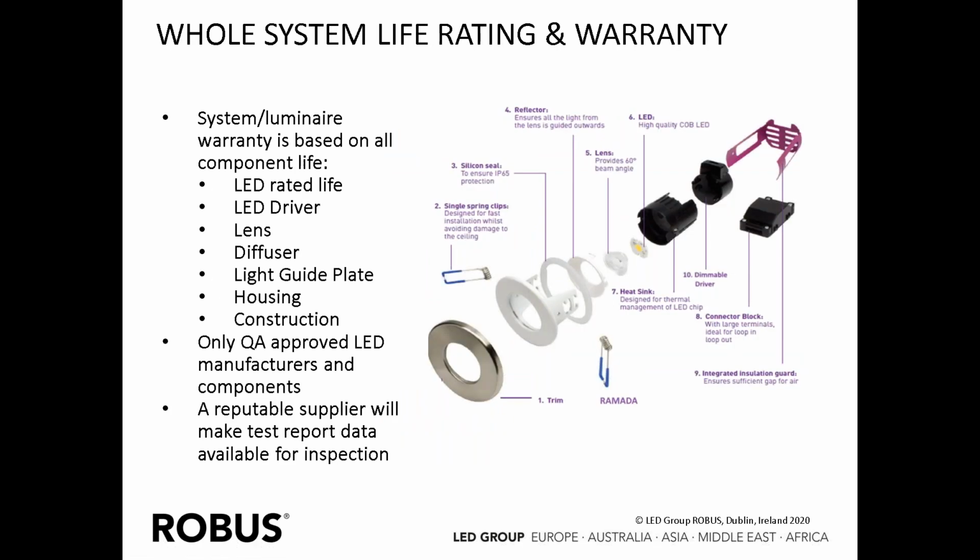Okay, if we just finish up now with this last slide, and this is about whole system life rating and warranty. It goes back to one of the initial slides where we have every component part of the product itself, the luminaire. So the system or luminaire warranty is based on all component life. So that's the LED rated life, the driver rated life, the lens, diffuser, light guide plate, the housing. All of these component parts go into producing a warranty for these components.